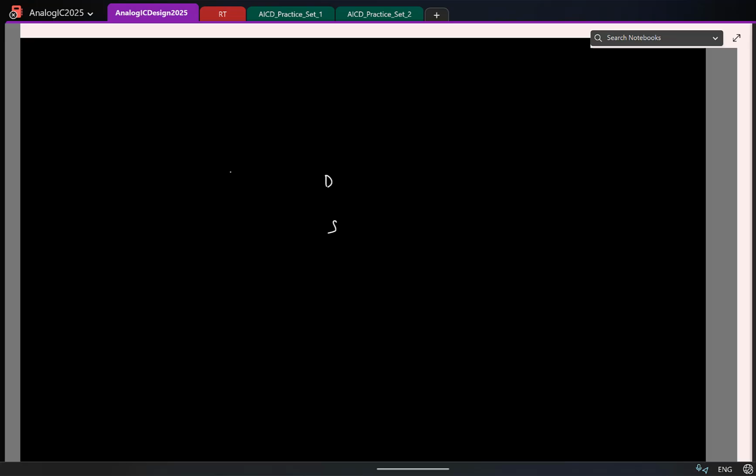And this current is in response to what voltage? Majorly gate to source voltage. So in a way, I can think that this is my cause, and the output effect is observed here. Which means I can apply input at the gate and see what happens at the drain. That is one possibility. I can also apply an input at the gate and see what happens at the source, or I can apply input at the source and see what happens at the drain. So we'll have three different possibilities.